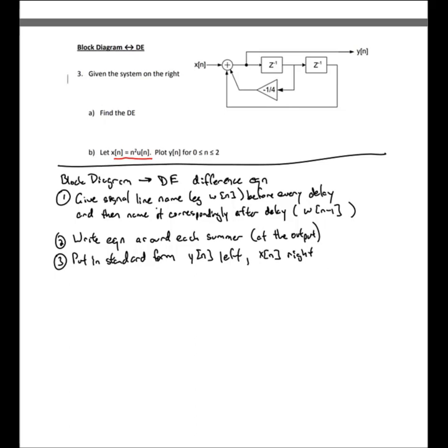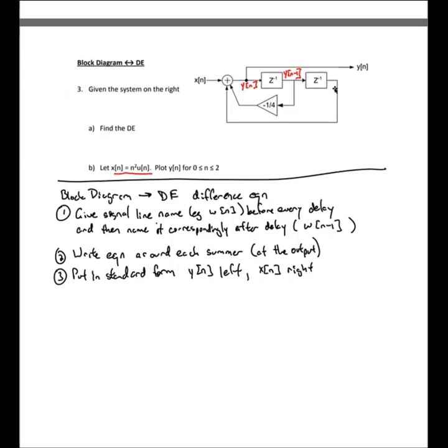So let's do it for this. We have a, looks like this is already labeled, right? We already know this is y of n. So this is one common mistake I see cadets do. They'll not use existing nomenclature, and then by adding new variables, things get just impossibly hard really fast. But if that's y of n, then this has to be y of n minus 1. So we don't really even need to then create a new symbol for before this one, because it's already labeled. So this is just going to be y of n minus 2.